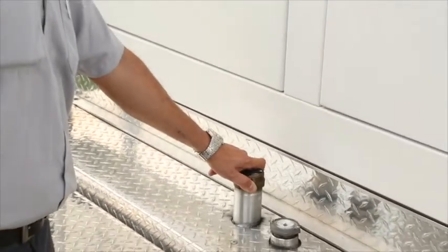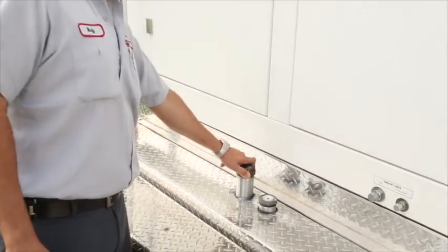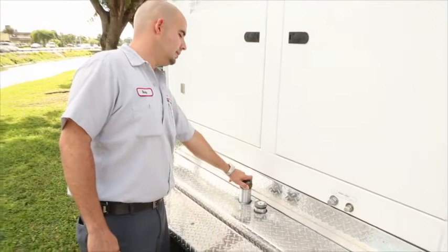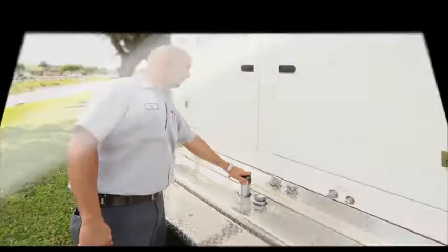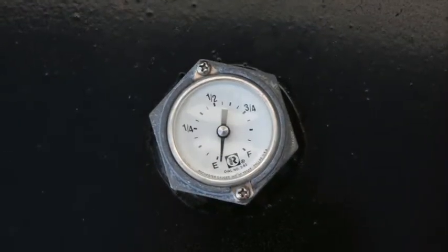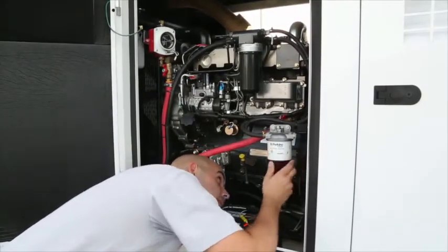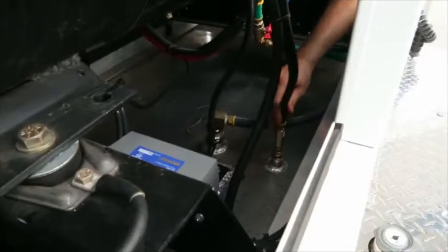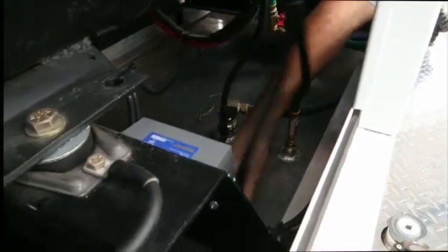Following a failure, the first course of action is to check fueling, with the first fuel check being to make sure there is sufficient fuel in the tank. All Tradewinds fuel tanks are fitted with a fuel level indicator. If the fuel level is okay, the next fuel check is to examine the fuel piping, fittings, and filter connections.